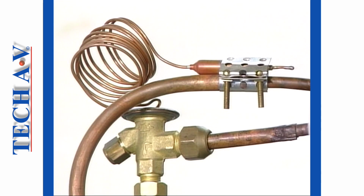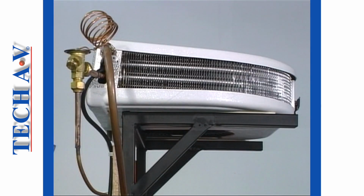The third component is the expansion device. This particular type is known as a thermostatic expansion valve, recognizable by a thermostatic sensing bulb connected by a capillary tube to the diaphragm on the valve body. The final major component, featured on our model, is the evaporator.